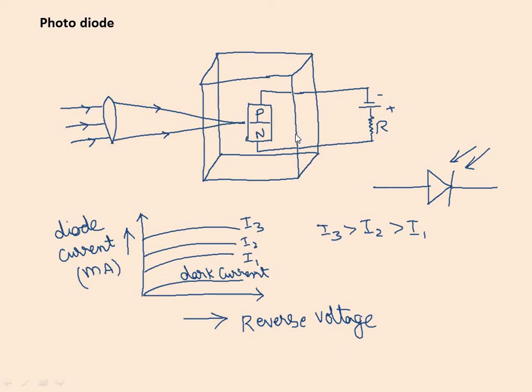If light is allowed to fall on such a reverse biased PN junction diode, additional electron hole pairs are generated in both P and N regions. It produces a very large change in minority carrier concentration and hence increases the reverse current through the diode. It is found that the current through the diode varies almost linearly with the light flux. Hence, light can be detected using a reverse biased PN junction diode known as a photodiode. A very well known thing for us, isn't it?